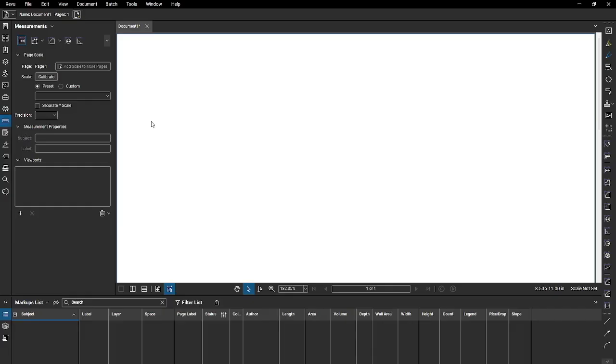The measurement panel and markup list are expanded, allowing you to access key functions and your markup data. On the right side of the screen, you will see a standard markup toolbar featuring commonly used tools, but under that, there is a toolbar featuring several measurement tools. The tool chest features a markup tool set designed explicitly for takeoffs in various disciplines. You can use these custom takeoff tools or create your own, which I will display in another video.